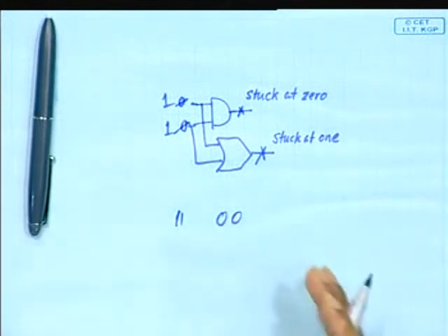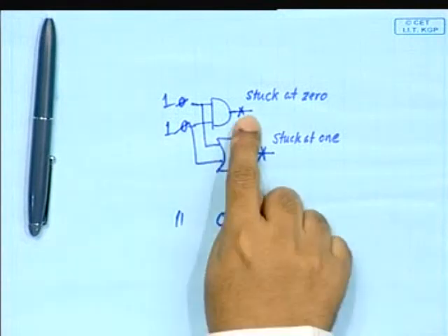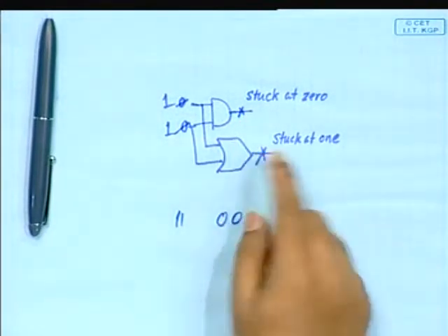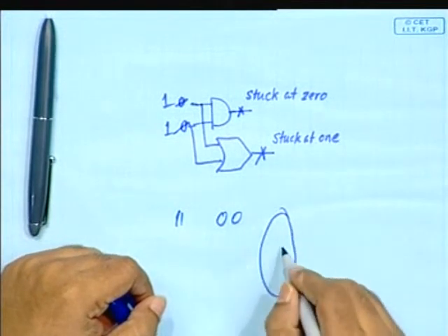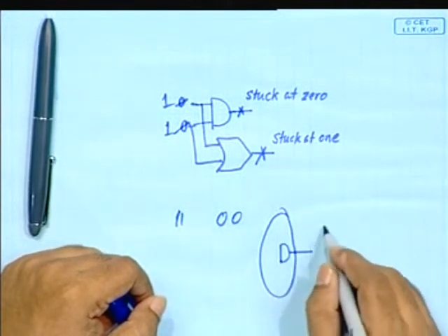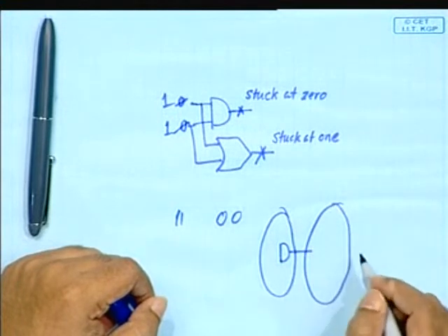So in a large circuit, the challenge is to determine what is the minimum set of test vectors by which you are able to sensitize all of these faults, right? And then it's not just sensitizing the fault, it has to be propagated up to the output, because here the fault that I was examining was at the output, right? But the fault may be somewhere in between. There may be a combinational logic here, and then the output of this gate is going into another combinational logic, right?